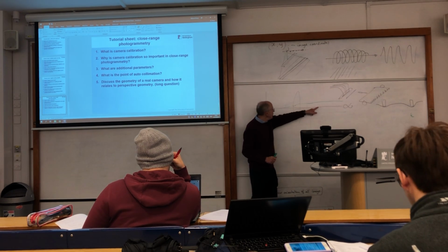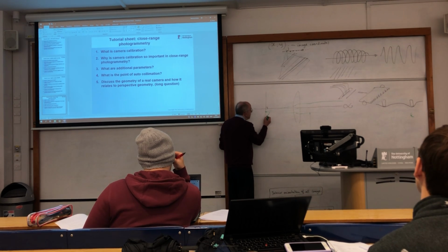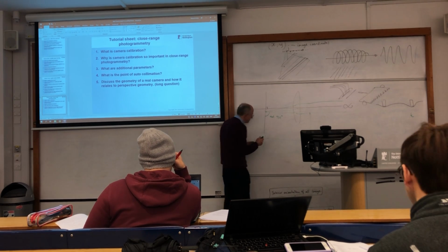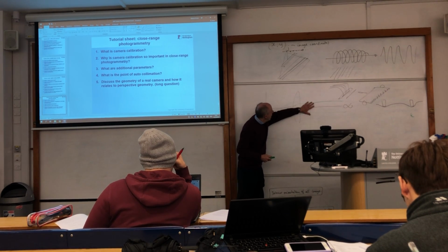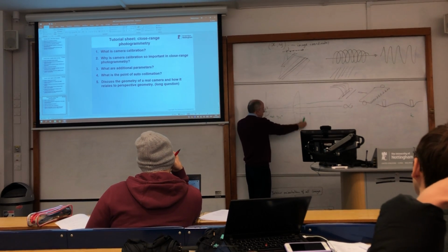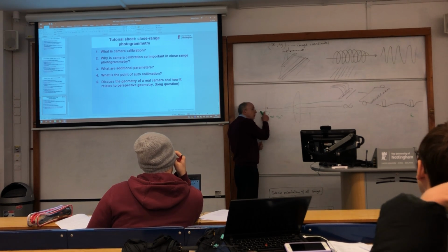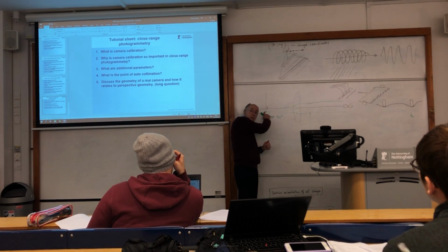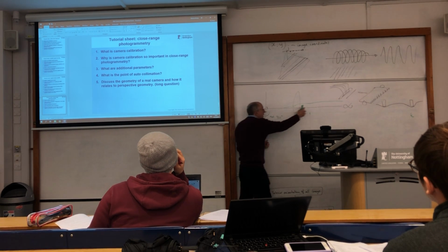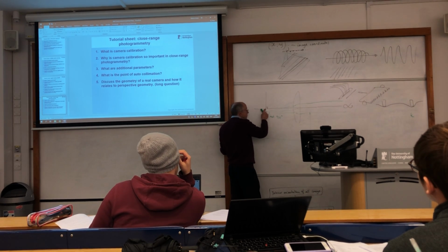Here, we haven't got that. That chief ray has come through the lens, and that is not 90 degrees. These are 90 degrees to the focal plane, so they are coming in at 90 degrees, but that is focusing on a different point. You see the subtlety and the difference? Alright, the perfect camera comes through focus, and that is where the principal point is.